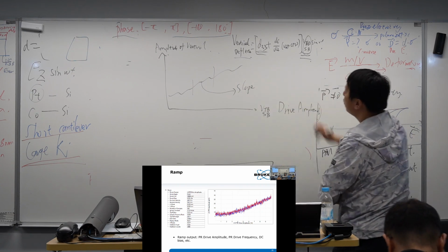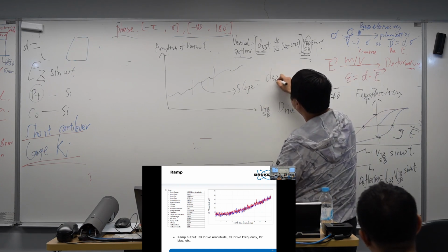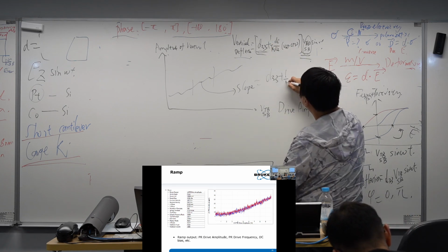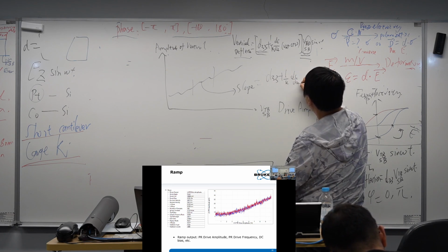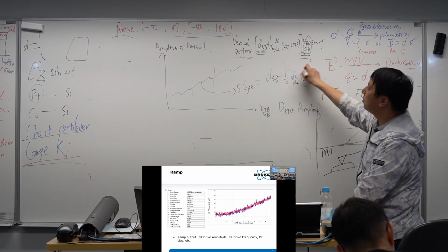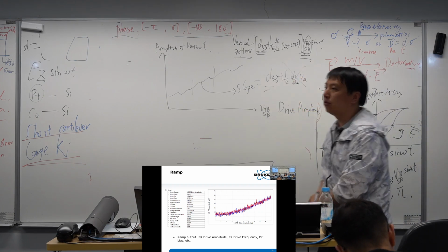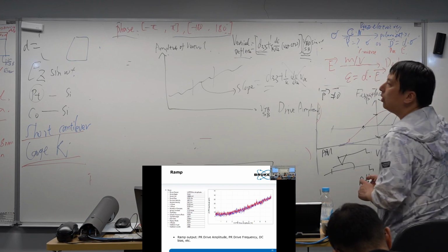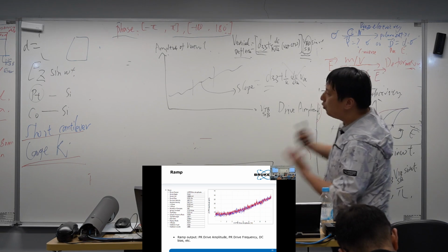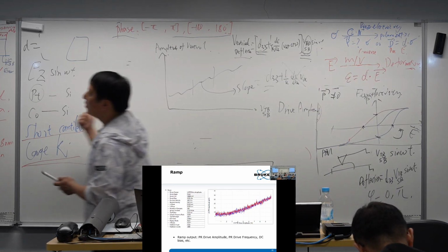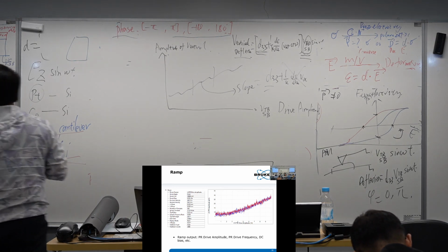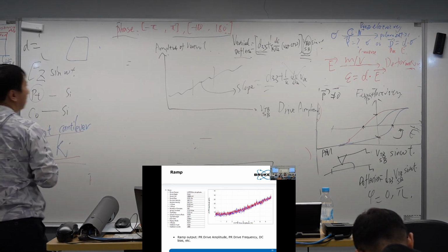The slope should be d33 plus, I'm sorry, there should be a 1 over k, dC over dV V_DC, right? So if this one is cancelled, then the slope will be d33. But of course, in a real experiment, it's harder to cancel this one. So if you really insist on getting d33, we do this kind of curve. It can be done in our experiment.